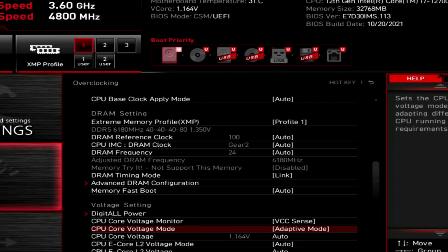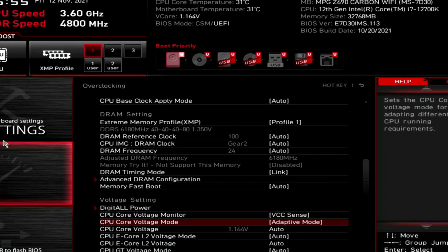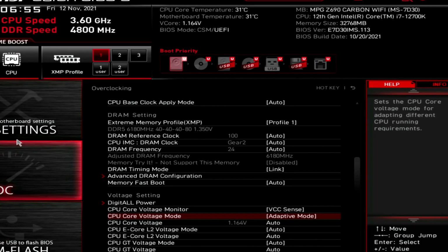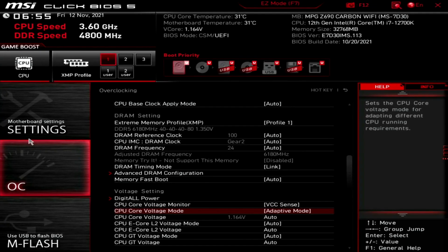While most of these auto rules are definitely very useful in helping to make the overclocking experience go more smoothly, they're not always perfectly tuned. In a lot of cases, you'll find that these auto rules are more focused on making it look stable and making your system boot up after an overclock than they are focused on running really healthy voltages. For example, I've seen motherboards adopt CPU voltage auto rules for ratios above the default maximum turbo ratio. If you're going through the process of finding the voltage frequency curve, you may think the CPU has factory fused settings for those ratios, even if they don't. So it's important to keep an eye out for these auto rules.